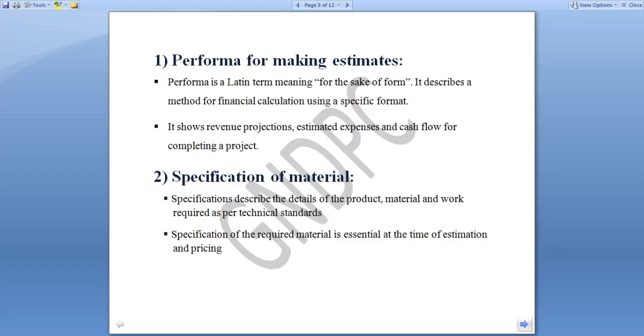Now, it will be very difficult to purchase a material from the market without the knowledge of these specifications. We can take an example, say for the electrical installation of a holder, we need to choose a specific type of holder. Now, in the absence of all the detailed specifications, it would be very hard for the shopkeeper also to provide the correct material because there are a number of holders present in the market, say pendant holders, baton holders, or screw type holders. Thus, the specification has a high significance.